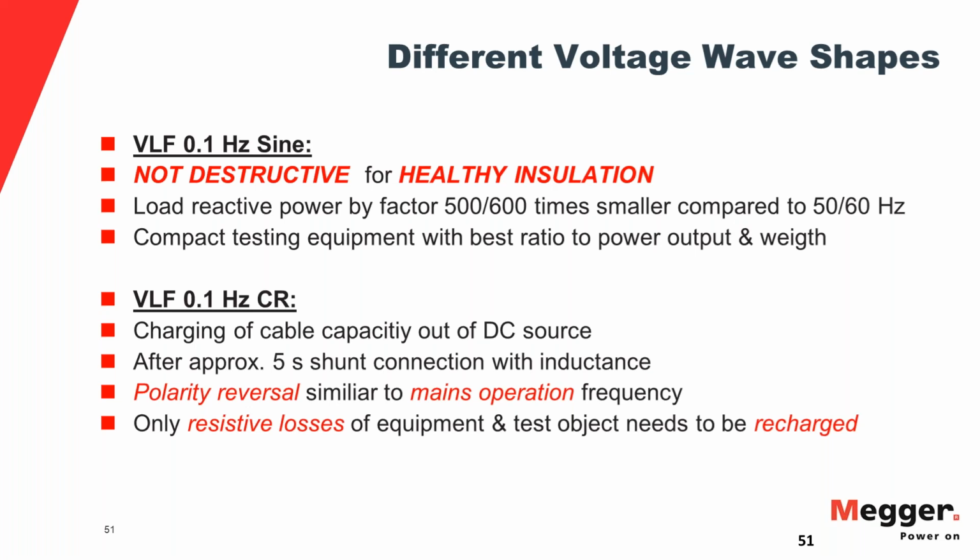And both VLF waveforms are also suitable from a theoretical point of view because their reactive power demand is so much less. So it's kind of damped AC. You need a fairly small DC source to charge the cable and then cause the resonance. So you don't need a lot of power in the field to charge the cable to do the testing. And it's the same with VLF because of the frequency, the reactive component, the apparent power that you need to charge the cable is so much less.